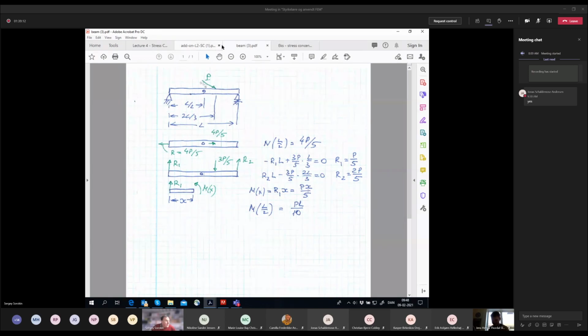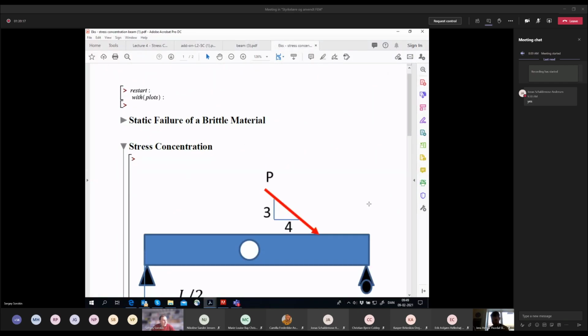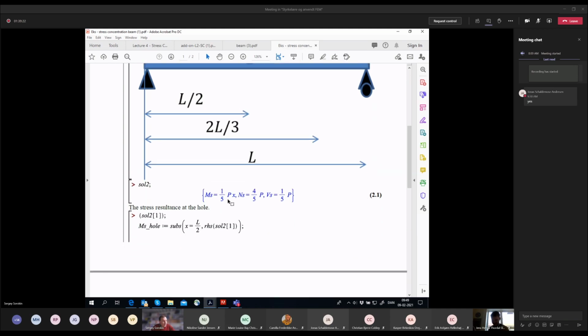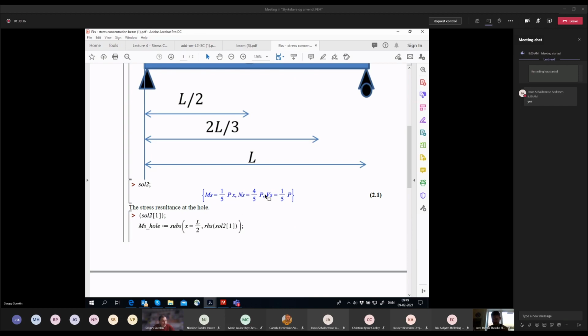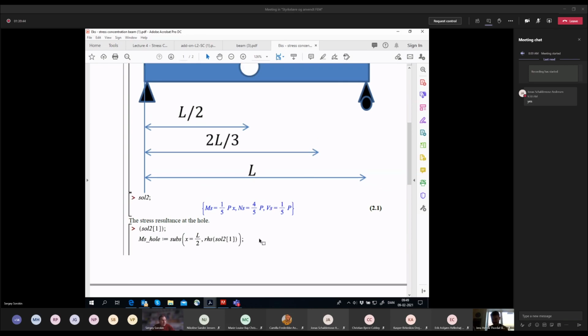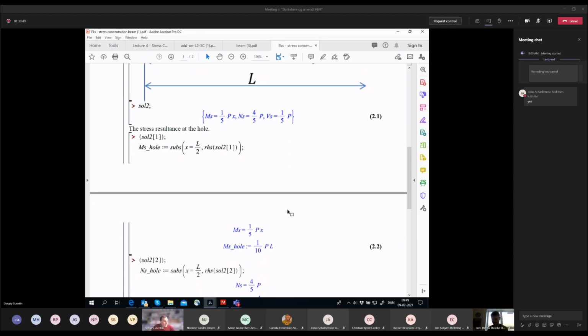So we go to this. Oh no, it's not this one. Yeah. So this is this picture again from Johnny Jacobson, and he already gave these things. This is actually why I decided to clarify how it's obtained, how I have this 4P5 and PL10, because he gives them for granted. And this shear stress is not needed, because as I told you, in this analysis of stress we ignore shear stresses. They are negligible.